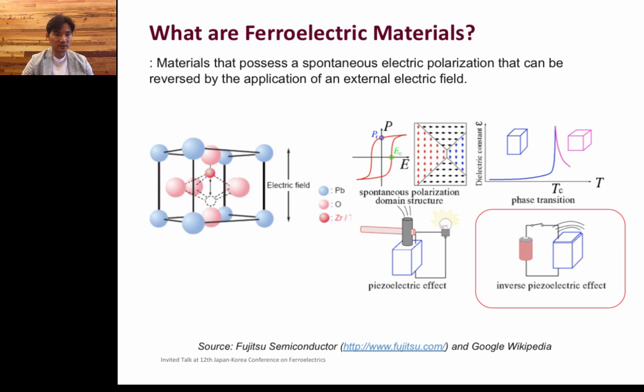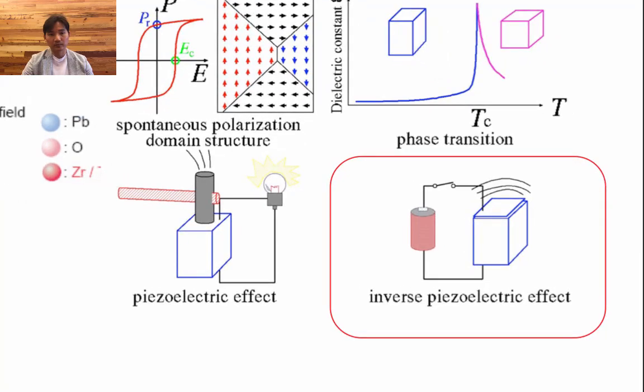And ferroelectricity is coming from spontaneous polarization, which can be switched by external field application. So you have a hysteresis loop that you can see on the right side. In addition to that, a bigger category is piezoelectricity. The piezoelectric coefficient will switch its sign upon change of polarization because polarization and D33 are linearly coupled.